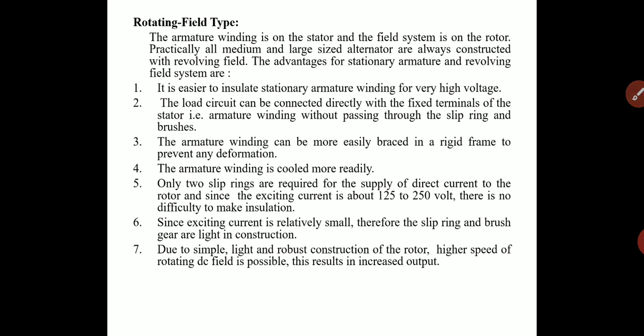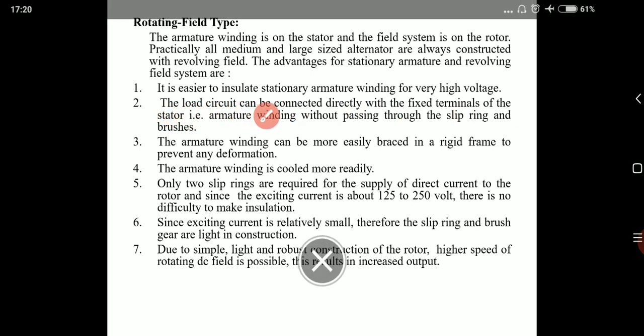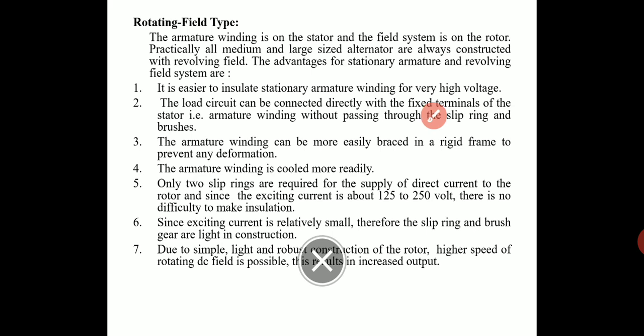The second advantage is that the load circuit can be connected directly. This one I already explained in the first advantage part. The load circuit can be connected directly to the fixed terminals of the stator, that is the armature winding, without passing through slip rings and brushes.